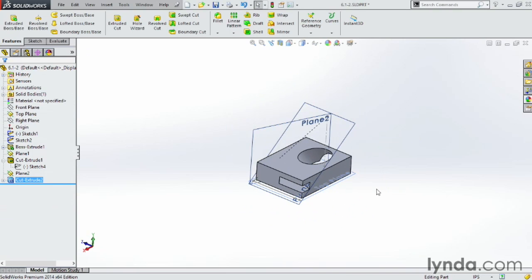Planes are the foundation of sketches, and in order to build a complex feature or higher level features like lofts and sweeps, we need to understand the basics of creating new planes. There are up to 3 reference values used to create planes. However, we can use as little as 1, depending if we're choosing either a point, a line, or a plane as our reference value. For instance, a line already has 2 endpoints, so that counts as 2 references.